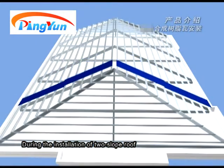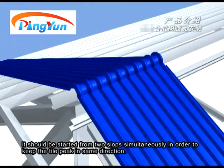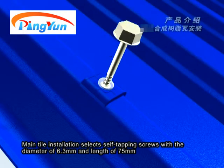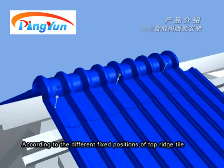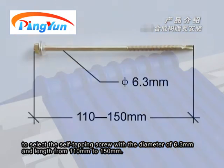During the installation of two slopes roof, it should be started from two slopes simultaneously in order to keep the tile peak in the same direction. Main tile installation selects self-tapping screws with a diameter of 6.3 mm and length of 75 mm. According to the different fixed positions of the top ridge tile, select self-tapping screws with a diameter of 6.3 mm and length from 110 mm to 150 mm.